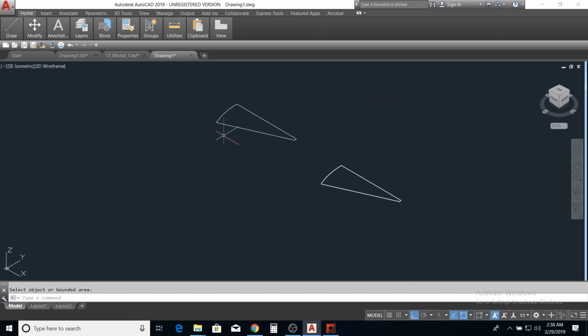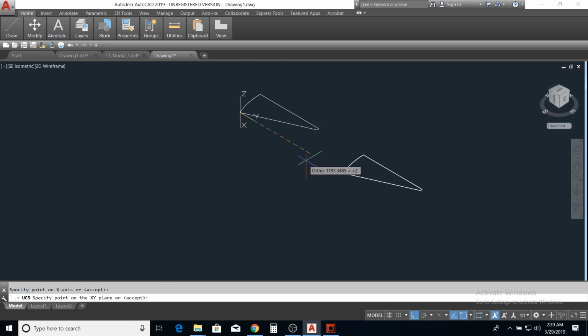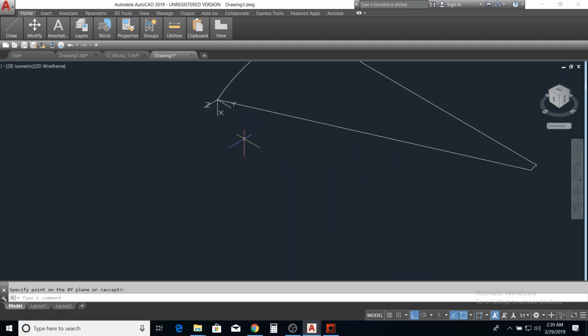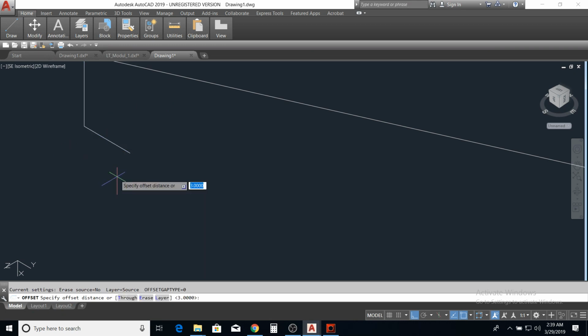What I'm going to do next, I'm going to draw maybe an L angle. But then I need to change my UCS. L down. So let's say I want to make a bend of 40, 30, 30. Okay, you can just join it. After that, go enter.